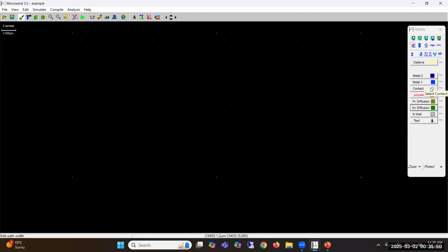You have contact that I explained, we need it to make any connection. Then you have the polysilicon, which is the gate, right? The polysilicon is the gate of NMOS and PMOS. Then you have P plus diffusion, N plus diffusion for source and drain. Then we have N well, which we'll need for the PMOS substrate, right? And then we have this text. If you want to write something on the layout, you can use that text. And then on the top, you have this.